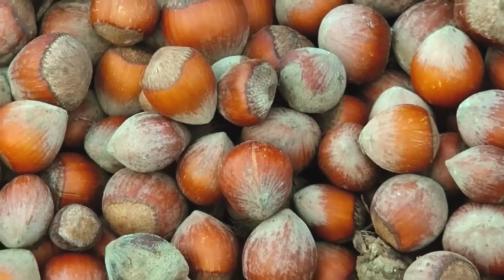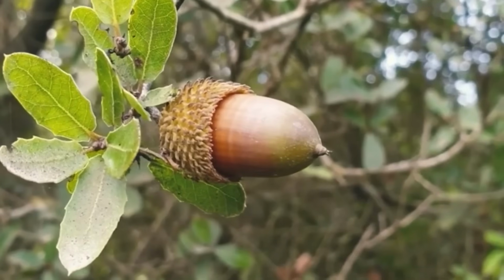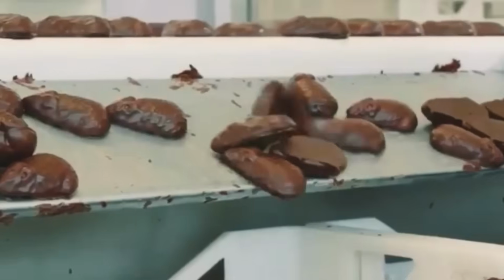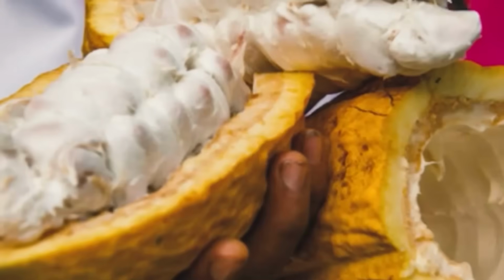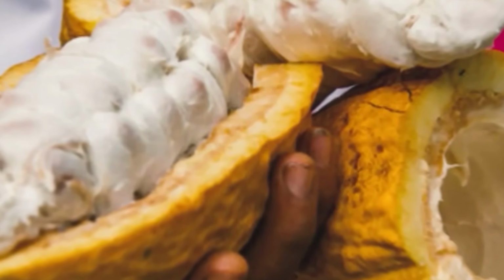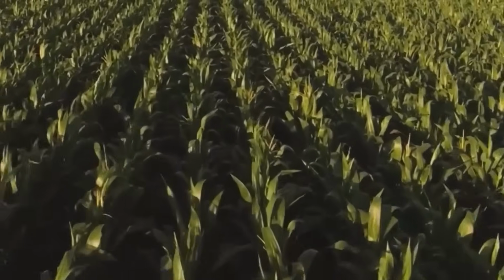Sanitation protocols are applied on a rotating schedule. Dough preparation lines are cleaned with dry brushing, followed by ethanol-based surface wipes. Cream handling equipment undergoes full CIP cycles involving alkaline wash, acid rinse, and sterile water flush, validated with conductivity and pH sensors. Wrapping and cartoning stations are cleaned with compressed air, brush downs, and isopropyl surface sanitizers. Swab samples are taken post-cleaning and tested for microbial load.